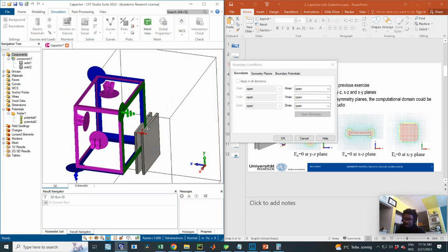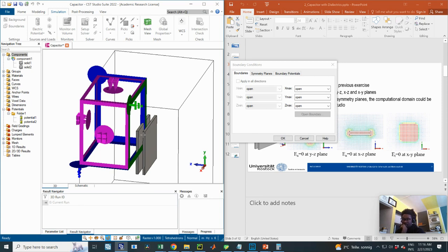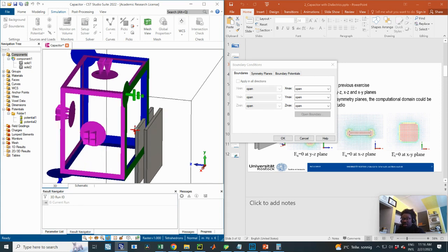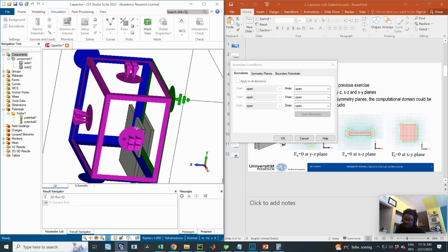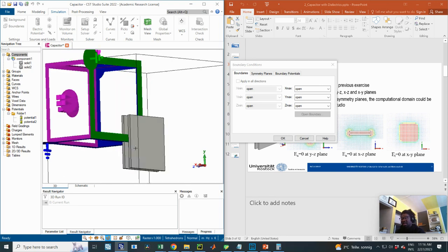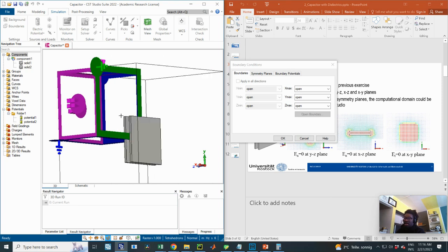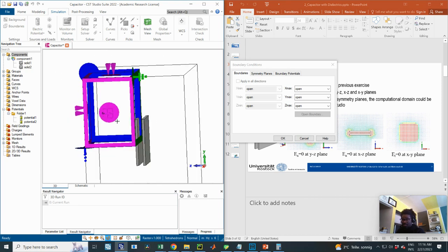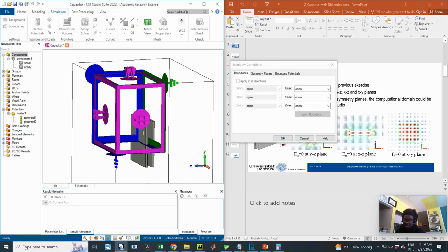Because of the symmetry conditions, when you apply your mesh, only this quarter of the geometry is going to be meshed and then mirrored over the other side with the appropriate boundary condition. So that's one use. It reduces the computation time for the whole model. You could compute for just this quarter and then mirror it, and that's okay with the appropriate boundary conditions.